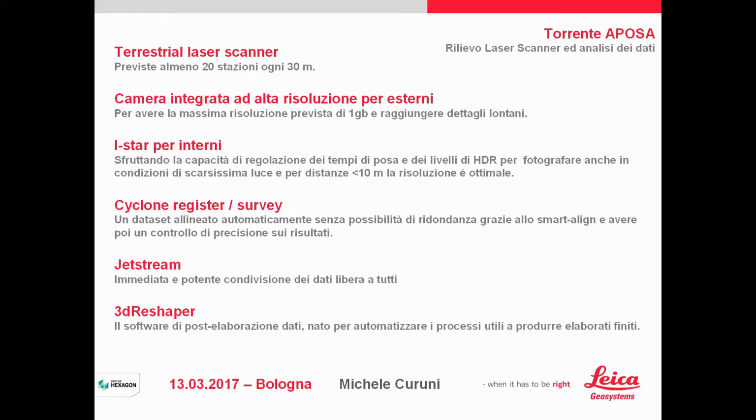So software, I used Cyclone Register because it was the first version that imported the iStar images in an automatic process, without doing it manually point by point, and that was terrible for 30 stations. So the automatic process is very, very appreciated.